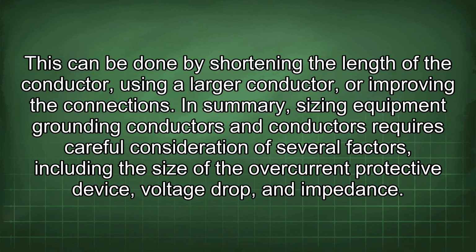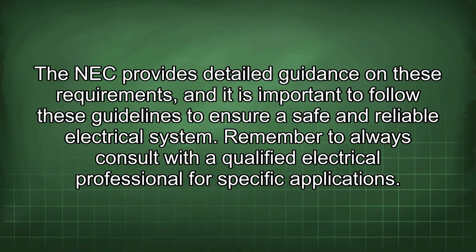In summary, sizing equipment grounding conductors and conductors requires careful consideration of several factors, including the size of the overcurrent protective device, voltage drop, and impedance. The NEC provides detailed guidance on these requirements, and it is important to follow these guidelines to ensure a safe and reliable electrical system. Remember to always consult with a qualified electrical professional for specific applications.